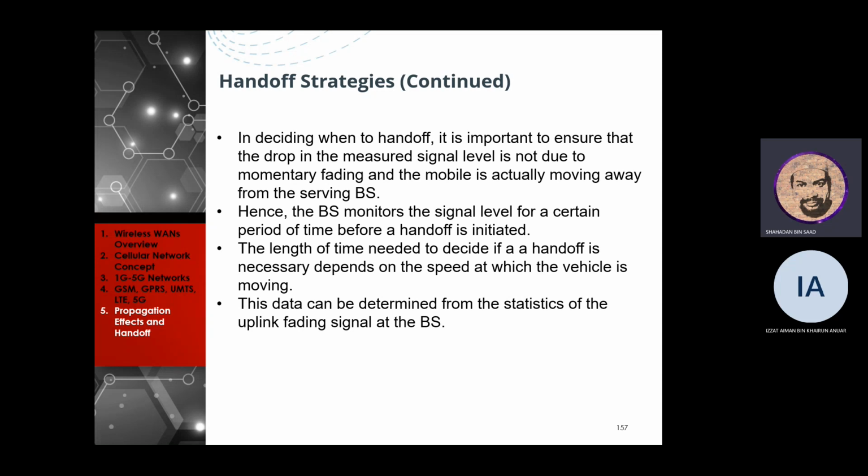Okay. So in deciding when to hand off, it is important to ensure that the drop in measured signal level is not due to momentary fading and that the mobile is actually moving away from the serving BS.